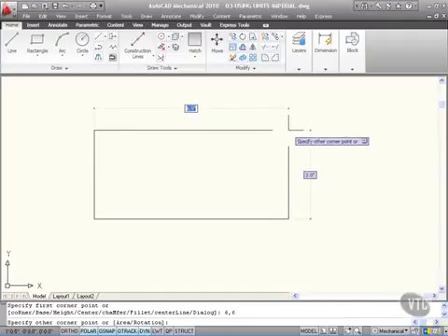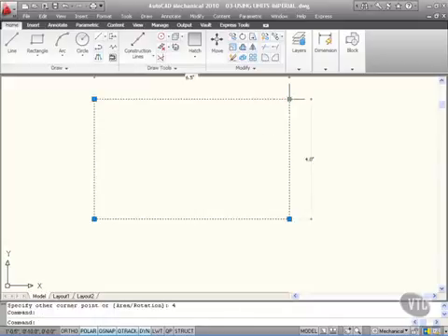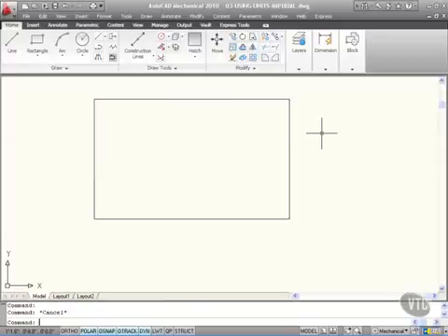So I'm going to say that I want the actual length along the x-axis to be 6.5 inches. I then press the tab there and I want that to be 4 inches. As soon as I press enter, it draws my rectangle, and my rectangle is now, when I click on it, if I hover there, you can see 6.5 inches by 4 inches just by hovering over one of the corners after I've selected the rectangle I've drawn. So as you can see there, that's using imperial units, feet and inches. So you just type in the value you want, job done.